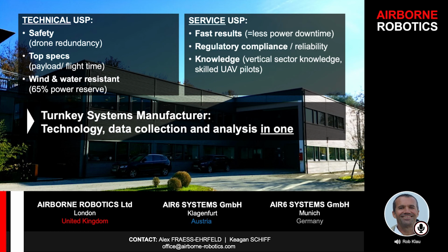Colorization requires a camera with your Lidar, so that you can then match pixels to points on your LiDAR points. So then you get that realistic, natural colored point cloud. And then that's before even getting into classification, separating out power lines, trees, ground, buildings, cars, people, etc. So loads you can do with billions of dots.